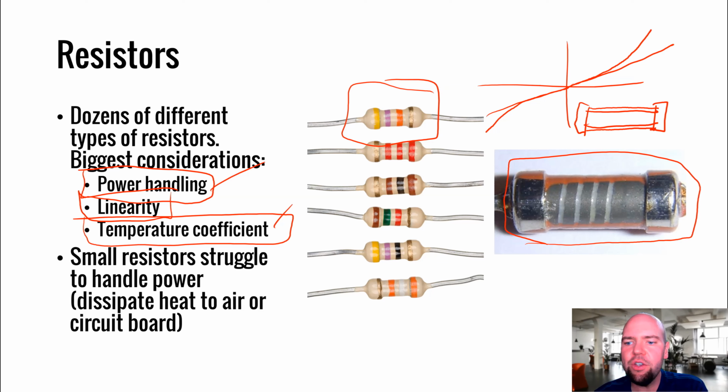And the way that you change the resistance is you essentially scratch a little channel in this carbon film. So you spin this resistor, and while you're spinning it, you run a blade across the surface, and it scratches this line in here. If you think about it, what it's making is a little coil of conductor. So the slower you drag the lathe across this resistor, the longer and skinnier this carbon film is going to be, and the longer and skinnier the carbon film is, the more resistance it has. And that's how you make a resistor.